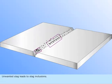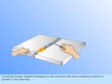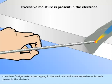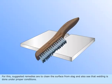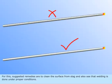Unwanted slag leads to slag inclusions. It involves foreign material entrapping in the weld joint and when excessive moisture is present in the electrode. For this, suggested remedies are to clean the surface from slag and also see the welding is done under proper conditions.